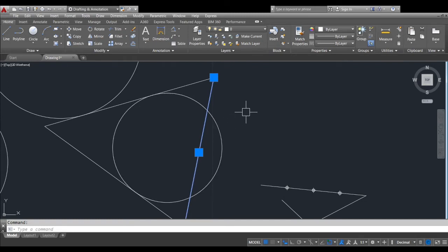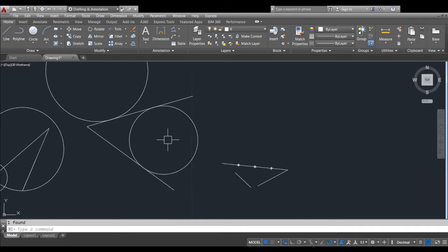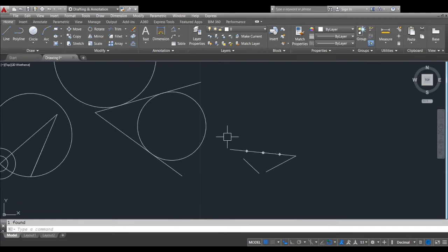If the previous command that you did is the erase command, we can just press the space bar. And then, that's it. No need to type letter E and then enter to erase the line if you're going to repeat the command that you have done.